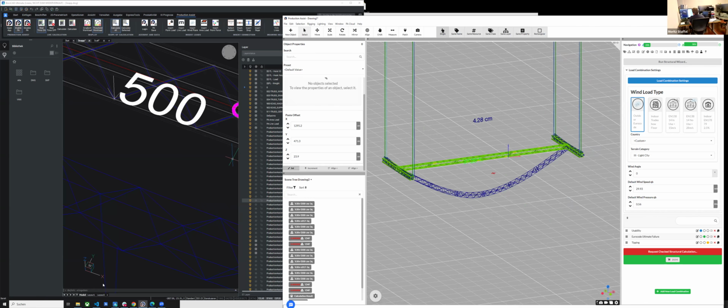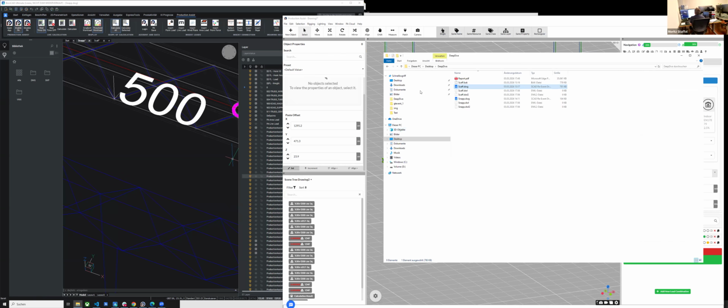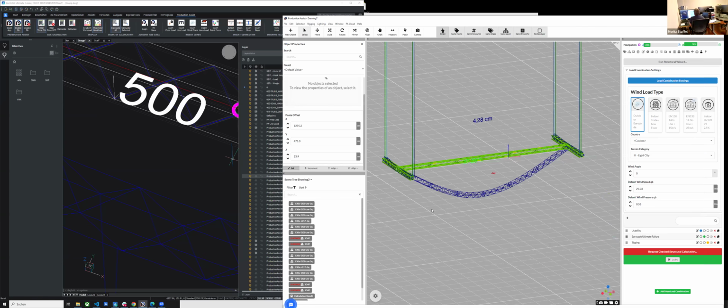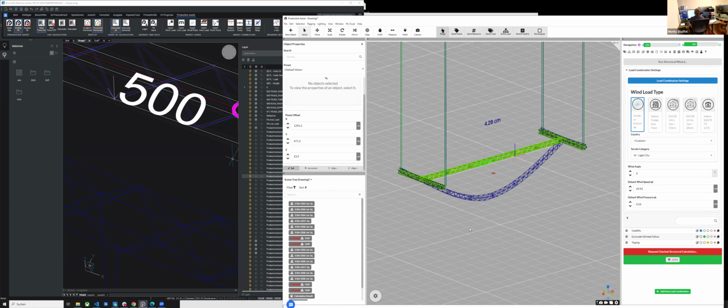All the blocks that we deliver in the production assist library are already prepared with this. So if you go to downloads, for example, there's a production assist library. We are adding more and more, so that you can directly use these things to come to a more accurate calculation of the trusses, especially if you hang it not purely horizontal or if you're using a lot of corners. This is really helpful for the calculation.